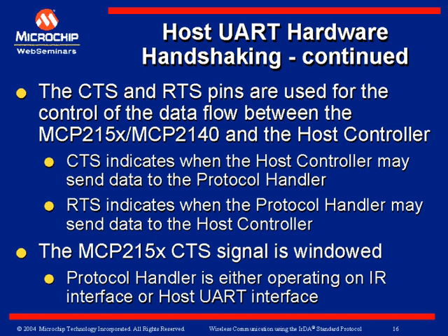In this interface, the CTS signal must be monitored by the host controller. This is so the host controller knows when it can transfer data to the protocol handler. Any data that is transferred while the CTS signal is high is ignored and will be lost. All right?